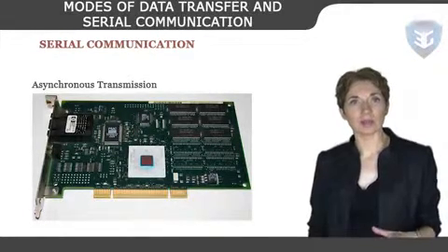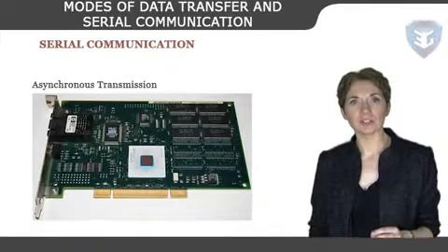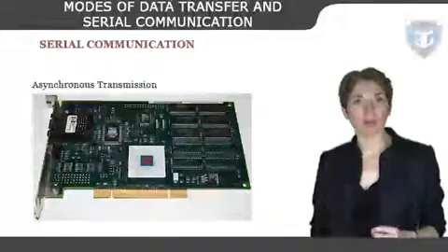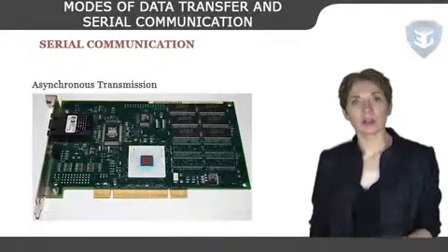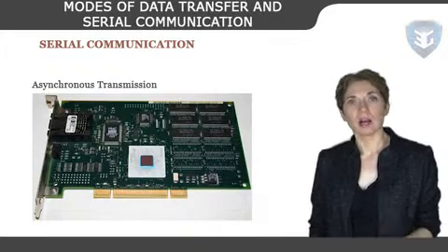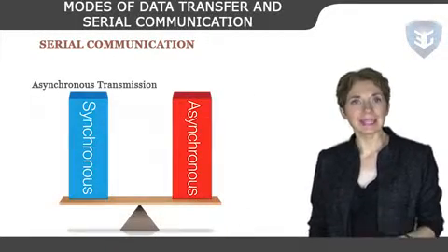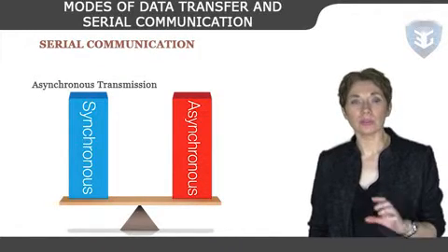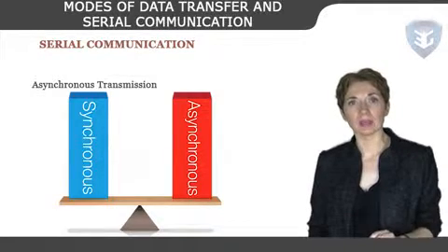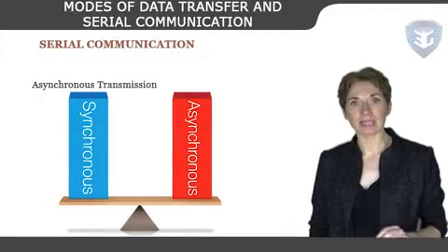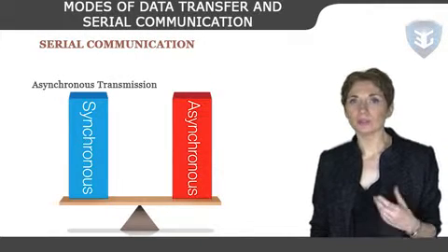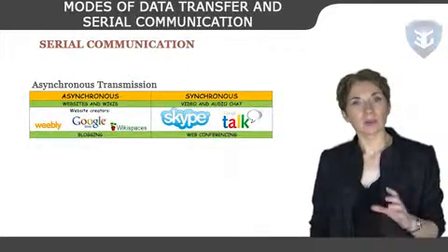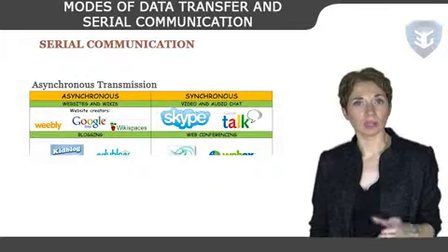Synchronous and asynchronous transmissions are two different methods of transmission synchronization. Synchronous transmissions are synchronized by an external clock, while asynchronous transmissions are synchronized by special signals along the transmission medium. Sending data encoded into the signal requires that the sender and receiver are both using the same encoding or decoding method and know where to look in the signal to find data. Asynchronous systems do not send separate information to indicate the encoding or clocking information. The receiver must decide the clocking of the signal on its own.